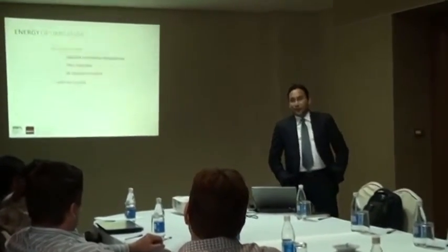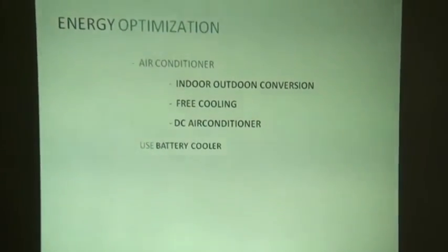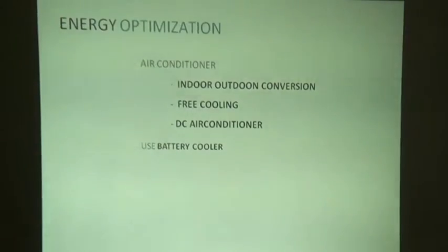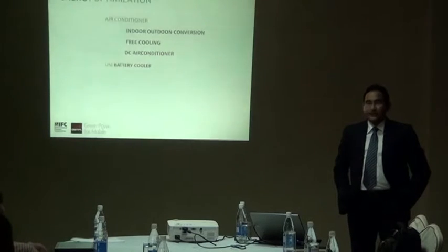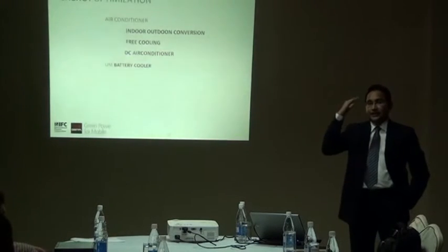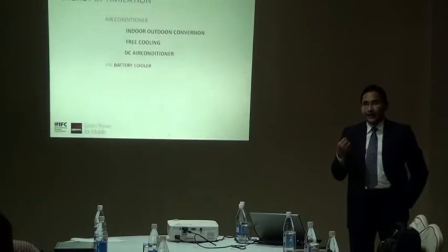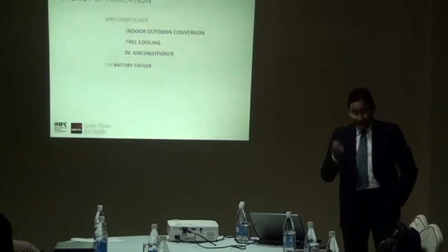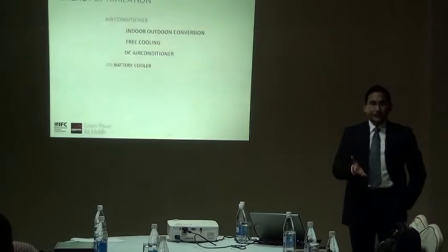Battery cooler, yeah, I think the battery guys are here. Well, this is one of the reasons for having an air conditioner. We all know the first question, if you are a mobile operator, the first question you will ask me is, if I'm not having an air conditioner, my battery will drain out, and I have to replace my battery in 2 years. Well, yes. If you're using a regular VRLA type battery, it's very temperature sensitive once the temperature goes higher than 22 degrees. So eventually you have to look at environment control opportunity, and eventually you have to have some conditioner system in place.